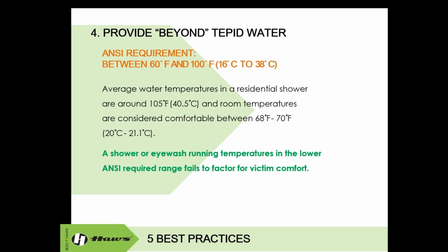As we mentioned earlier, you want to take tepid water a step further. Providing 60 to 100 degrees Fahrenheit is going to meet the bare minimum, which we would like to say is the ANSI standard. That is the bare minimum, but going above and beyond is going to ensure that there could be less time spent in the hospital, less lost money, and potentially lower injury.